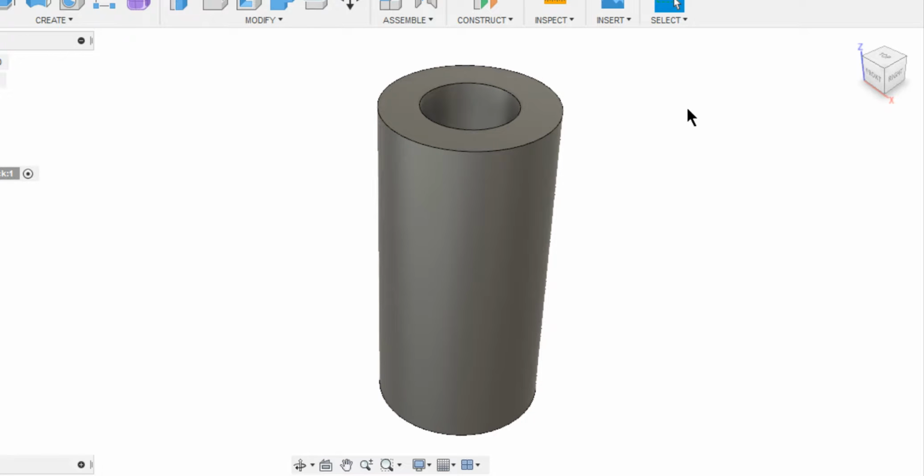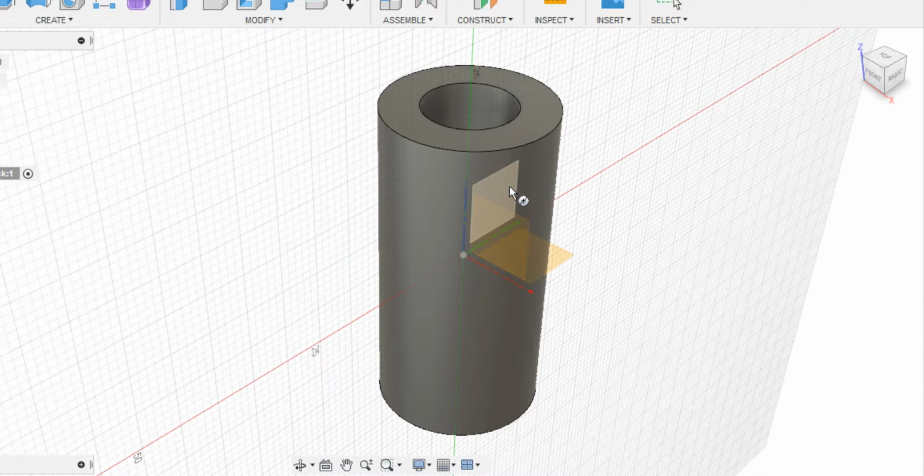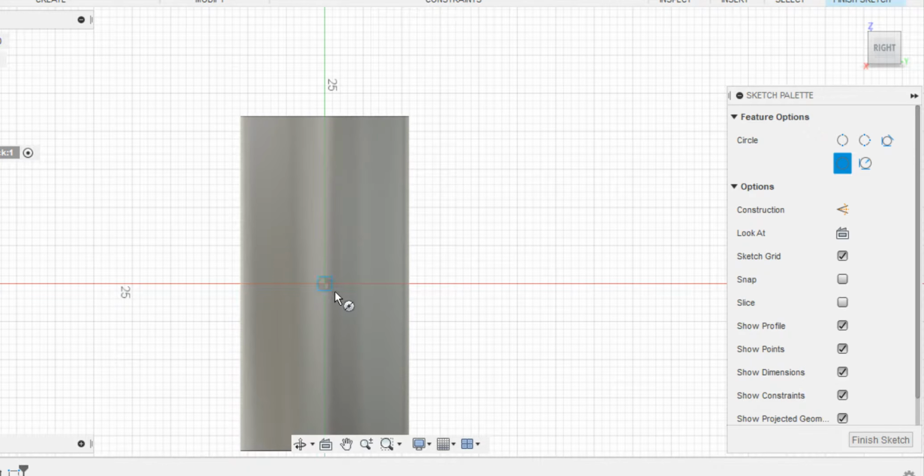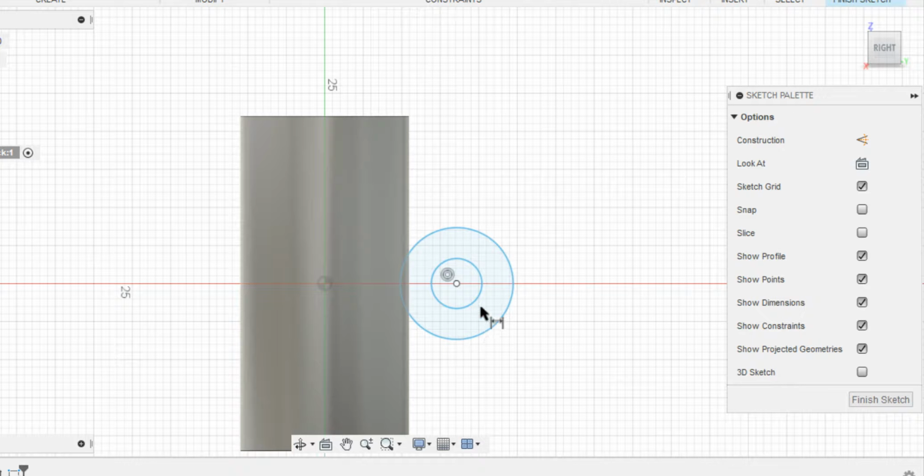Awesome. Repeat the circle but choose YZ plane for sketch and draw 2 concentric circles on y-axis. Let the inner one dia be 0.6 times d. The outer one dia be 1.1 times d.